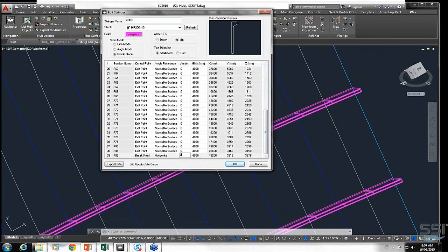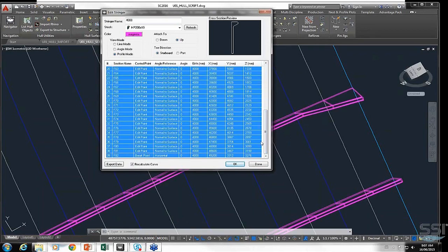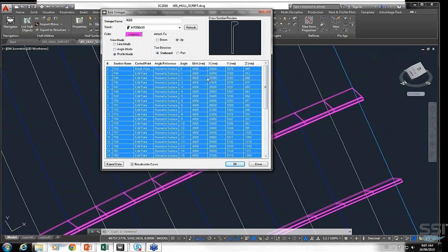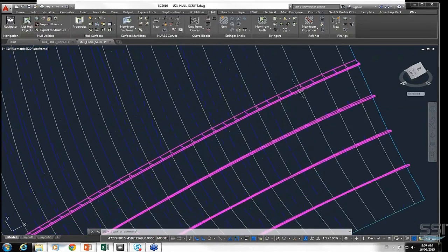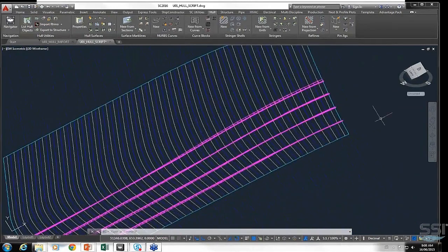So we're going to set that to 0, and you're going to see a pretty extreme directional change. So you see how right now it's angled harshly. We don't want that to happen. We want it to be more smooth. So what we'll do is select all of these points now. We go back up to the angle and we say evenly distribute angle between. And by doing that, it sets the information so that we have a clean, smooth twist. And you can now see how well that twists along.